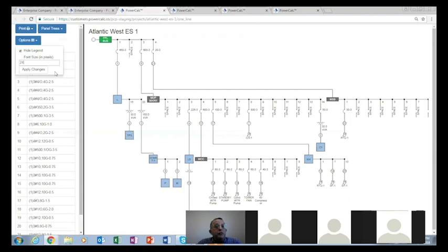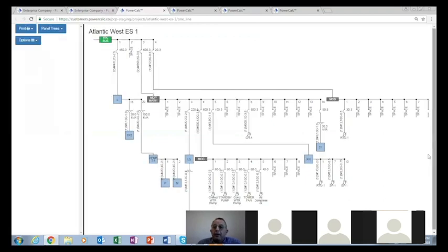So I can go ahead and change it, say, to 24, apply the changes. Okay, if I get your attention back to rooftop unit number 1, it took the tag designation 22 and listed the actual conductor size and enlarged the font a little bit to be legible.